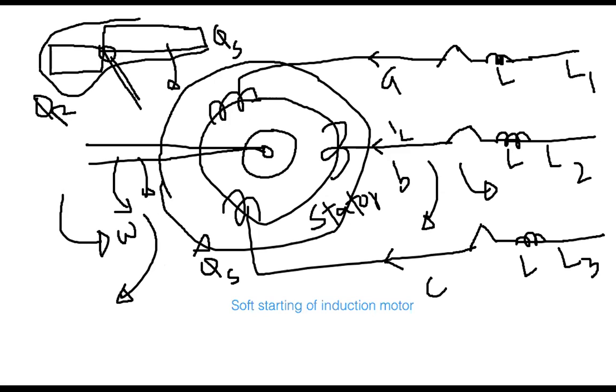Immediately you have to stop the motor. Immediately you disconnect. You stop the motor. And then you just interchange any two of the lines. You connect this one here and you connect this line there. You just swap any two of the lines. Or you make the connection this one here and that one there, and the rest is as it is. You just need to interchange two lines. You just swap any two of the lines.